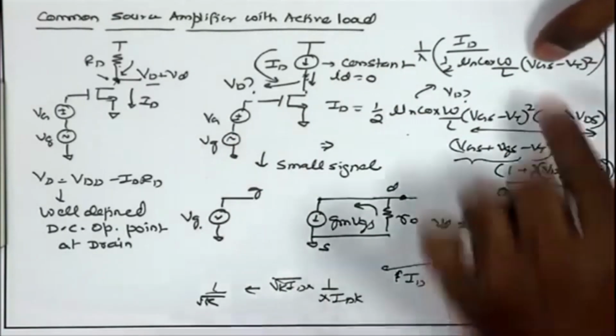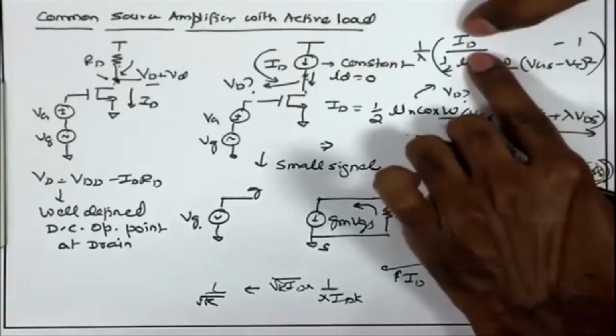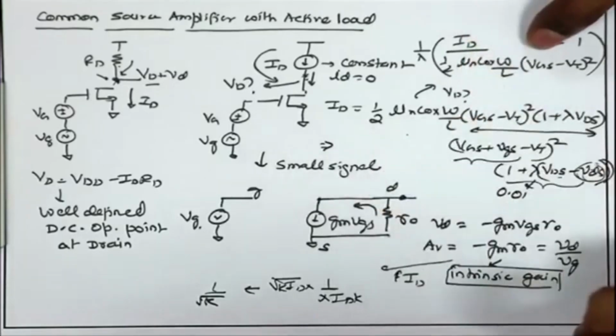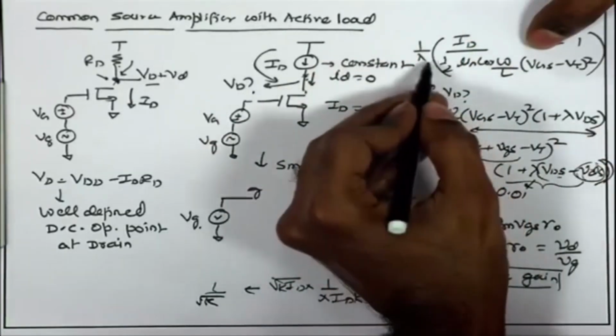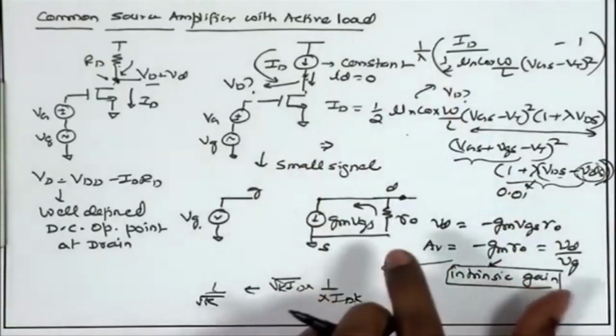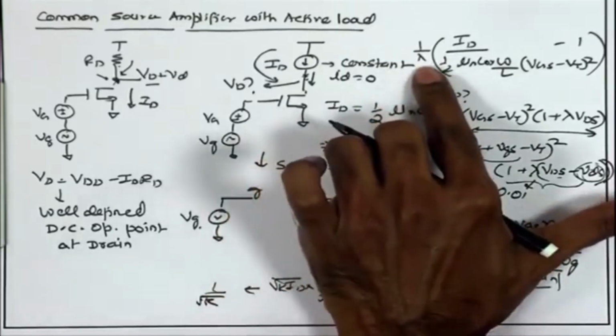Remember here what we are saying is Vgs is being fixed, we have the freedom to choose Vgs, we have used an ideal current source, so we have chosen Id. Therefore, this gives us that the Vd is dependent upon 1 upon lambda, and in general lambda is not a very precisely defined quantity.